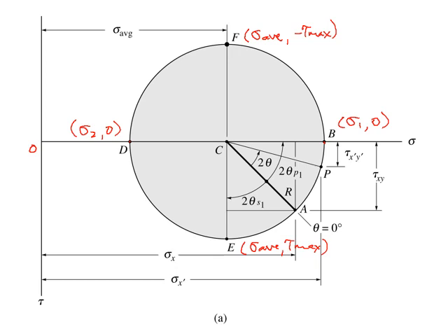Right. So since BC represents the location of the axis or the plane where sigma 1 occurs, the measurement comes from our reference, which is AC. That's the reference axis or x-axis. All the angles can be measured from there if you want to.